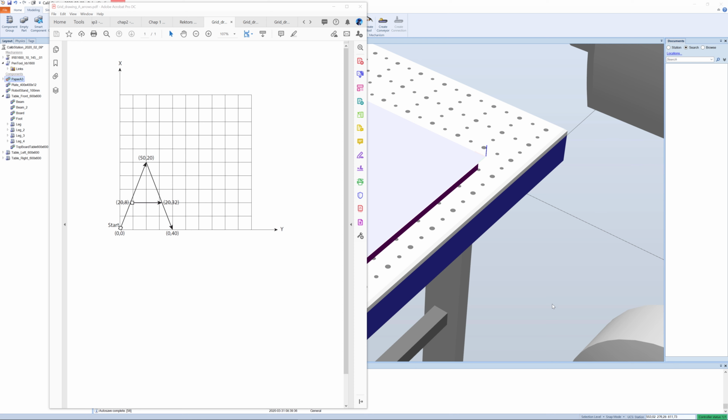But anyway, for the character A, here are the coordinates. We start drawing from this position 0, 0. We have X in that direction, which resembles a table from the robot's stand position, so to say, and Y in this direction. Then we draw like that down here. We have to lift the pen and draw from there to there. So these coordinates have to be representing robot targets to start up with, and then we continue from there.